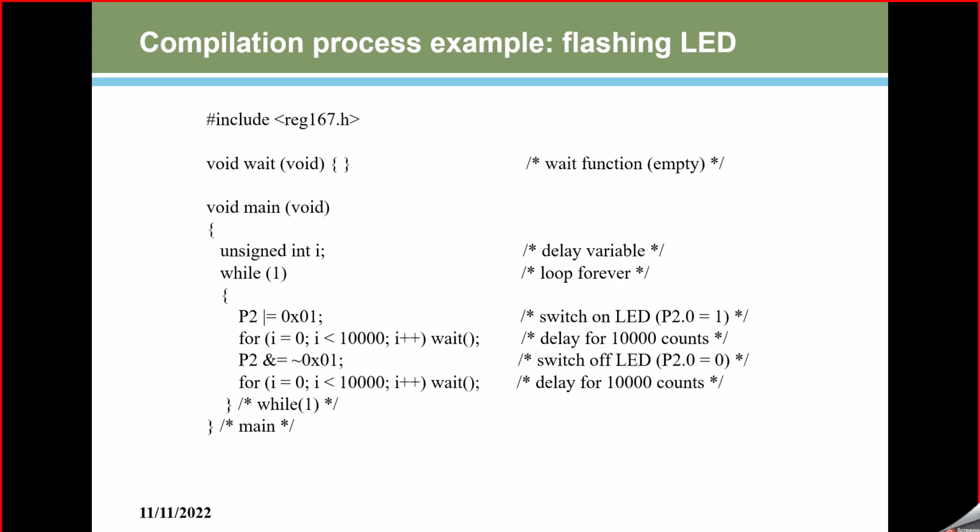Okay, this will keep on continuing as long as power is there in the microcontroller. That's why it is in a while(1) infinite loop. So after coming out of the infinite loop, it will be in main. Are you getting this program, which just toggles the LED in a controller? This is a basic microcontroller programming concept. We can simulate and check it in our Keil software.